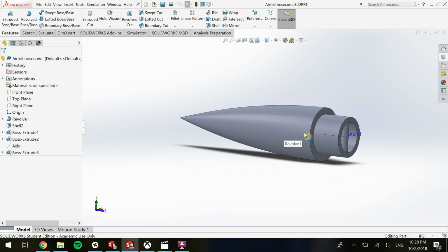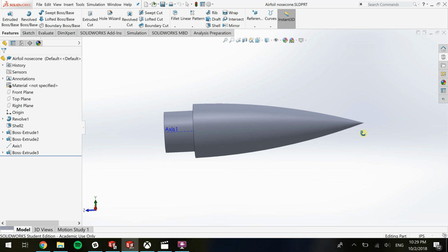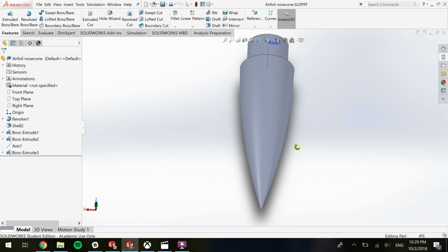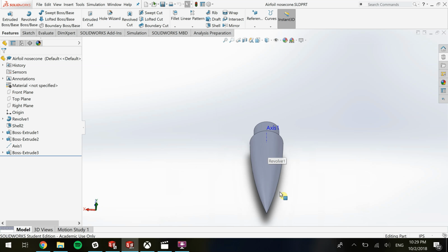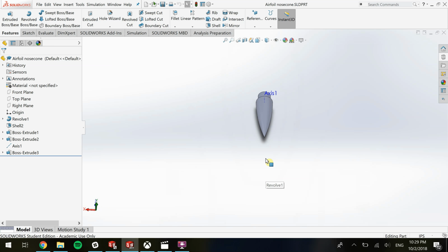The first thing we're going to do is learn how to navigate just around a part I already have. I highly recommend a mouse for this as it makes it much easier. So to look around, we hold down the scroll wheel and move the mouse. To zoom in and out, we spin the scroll wheel, and that's how you move from one side to the other side usually. If you're stuck on a laptop, you can use your arrow keys, and then Control plus your arrow keys moves like this, and your trackpad will zoom, but it can be quite finicky.